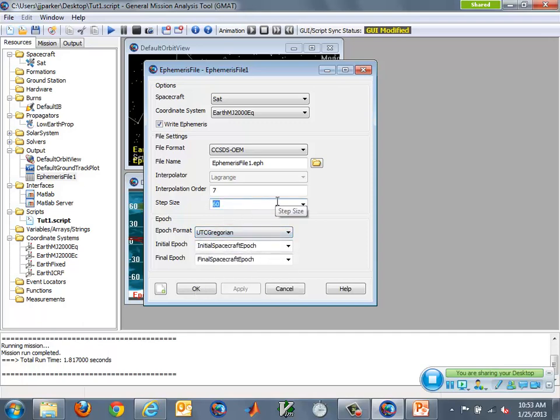Of course, this is going to beg the question: can you ingest Free Flyer ephemerides, STK .e files? We can propagate an SPK ephemeris, and that's the only format. Can you read in other formats? No, not right now. You can read a SPICE ephemeris, but no other. Not an .e file or a Free Flyer ephemeris file?